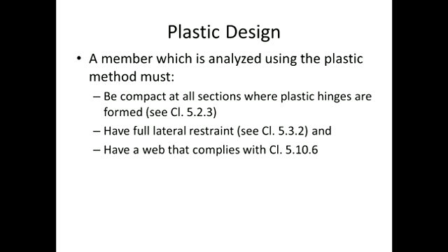So the standard also says that for us to be able to use the plastic method, we have to have full lateral restraints within the beams that we are looking at, and we also have to look at the web. And the web has to comply with certain conditions as well.